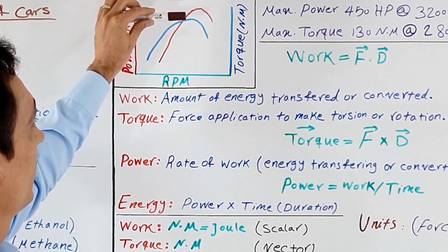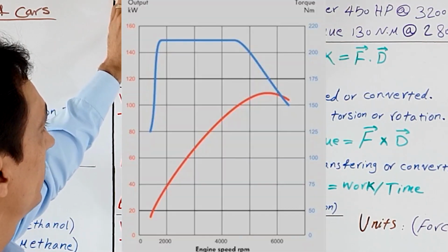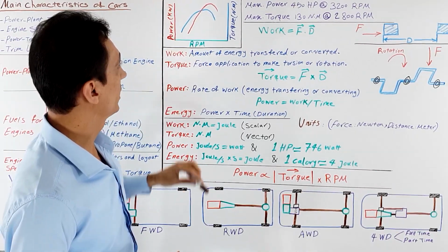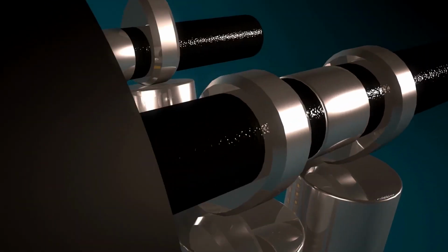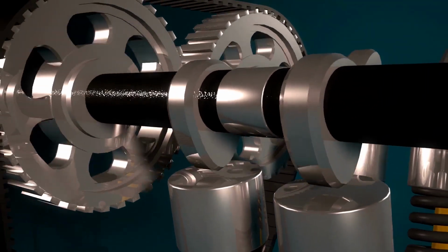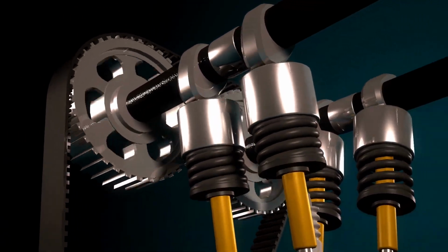In this case, engineers try to make this line as flat as possible at maximum by playing with features like boost regulation, valve timing, fuel injection duration, and ignition strategies.